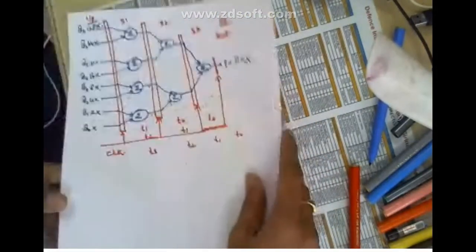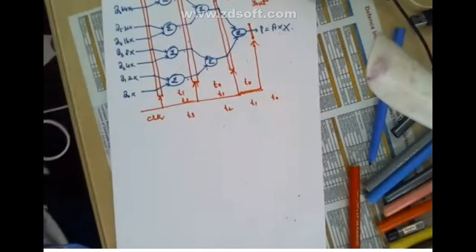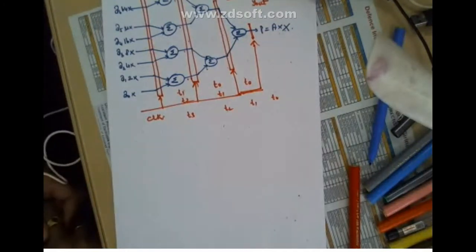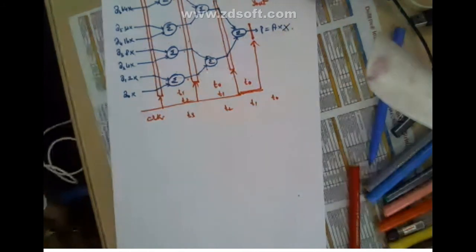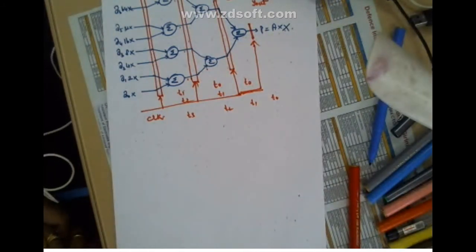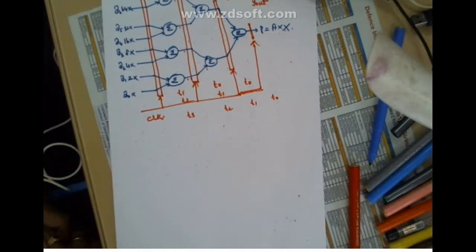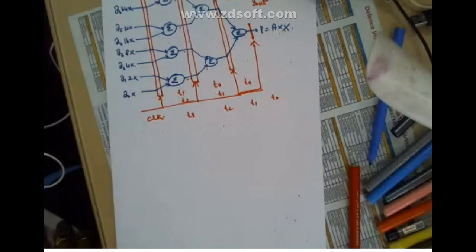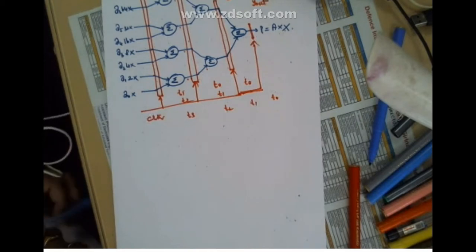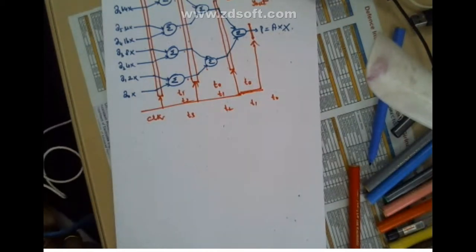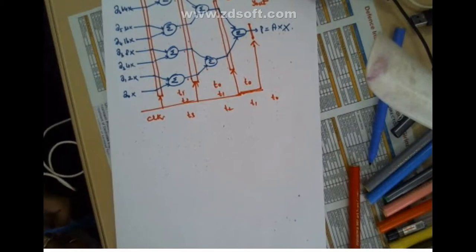The combinational circuit part is over. We need to realize all those things in our laboratory. Now we are moving into sequential circuits. But I already told you, a sequential circuit is nothing but some combination of combinational circuits only. There is no special element called a sequential circuit. The flip-flop and latch are also made up of basic gates only, but there is timing control. Because of the interconnection of flip-flops or latches, it is possible to maintain the circuit at one stable state, and to change that state, we need to feed the clock. So that is the idea.